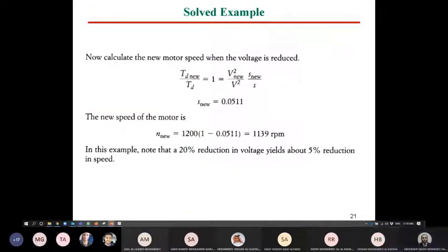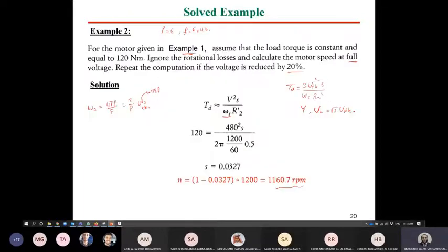Right. Now, guys, we calculated the machine speed at rated values. If the voltage is now reduced by 20%, what do we expect? What will happen if we reduce the voltage by 20%? In terms of maximum torque, what will happen? For the maximum torque, guys. Decrease. It will be decreased, exactly. Right, for the starting torque, is it going to decrease or increase?